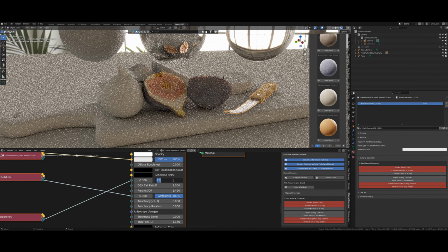Take a look that V-Ray uses glossiness for materials, and if we've got a roughness map, not a glossiness map, which is not used by default in Blender, we have to invert it to roughness, then the invert node will not be transferred, so you are going to use the correct one.